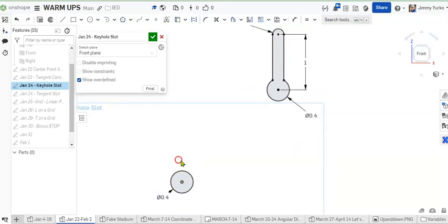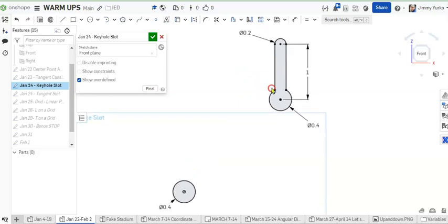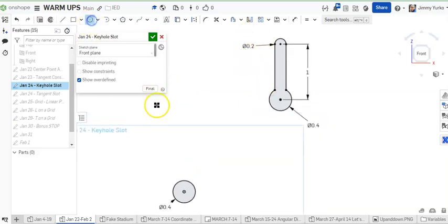so that I have that circle turned black. And then the next one we're going to draw is this 2/10 of an inch diameter circle. So circle tool, I'm going to hover over the origin, bring my mouse up, and you can see the vertical constraint will be applied when I click. So I'm going to go ahead and click now, move the mouse, and click and release, and type in the value before I do any other clicking. So 0.2, enter. And then the distance between them, center to center, is 1 inch.